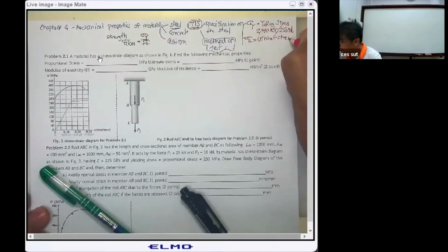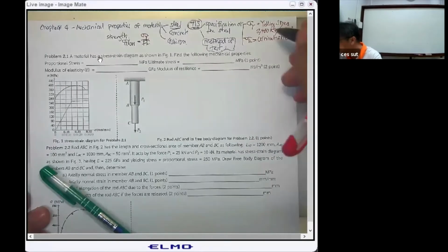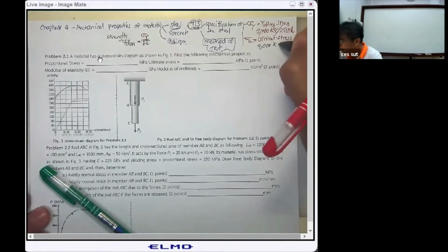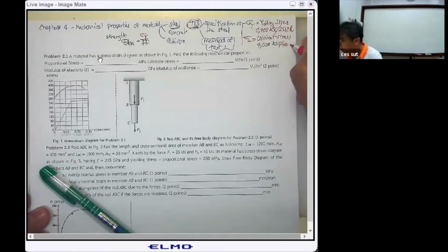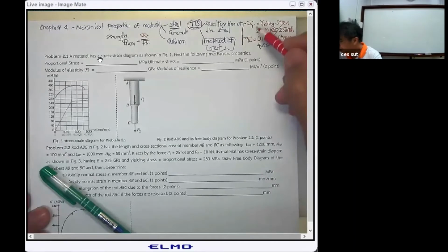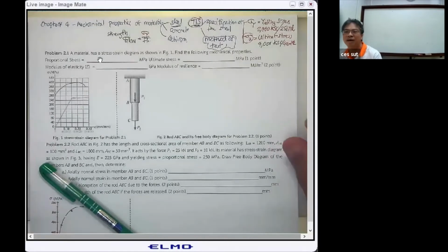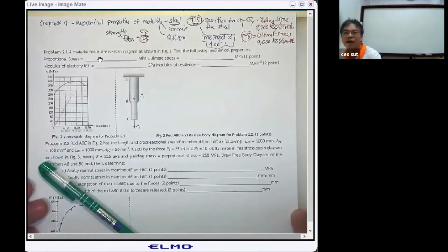stress of the steel. The ultimate stress, the TS says for the common reinforced concrete, is about 4,000 kilogram per square centimeter. That is just above 400 megapascal. The sigma sub u is specified in order to make sure that the ultimate or maximum stress of the material is higher than the yielding, and it is going to be another safety factor for the structure.